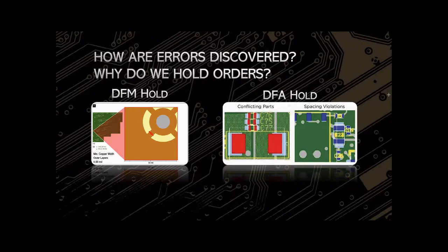We use your bill of materials, your XYRS, and your Gerber layers. And then we're comparing the BOM to the XYZ and vice versa, finding discrepancies between the two files. We're also using package models to overlay on your footprint, looking for layout issues.